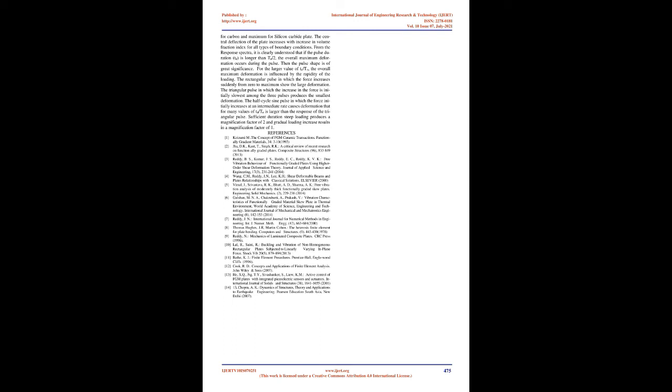The triangular pulse, in which the increase in the force is initially slowest among the three pulses, produces the smallest deformation. The half-cycle sine pulse, in which the force initially increases at an intermediate rate, causes deformation that for many values of Td/Tn is larger than the response of the triangular pulse. Sufficient duration steep loading produces a magnification factor of 2 and gradual loading increase results in a magnification factor of 1.